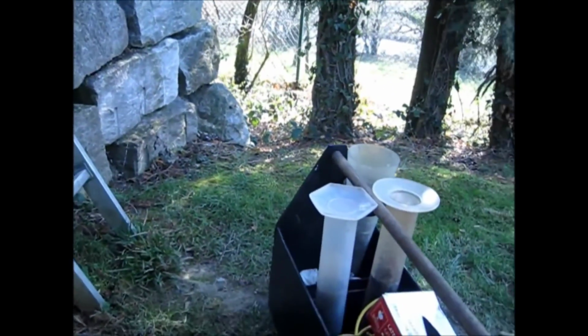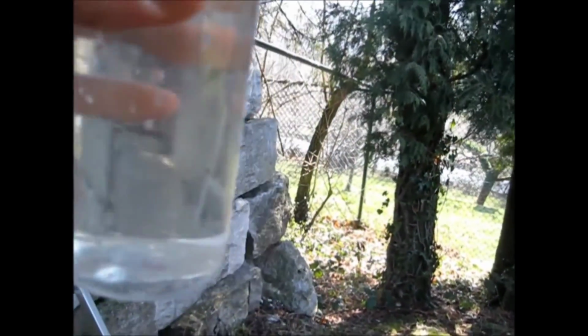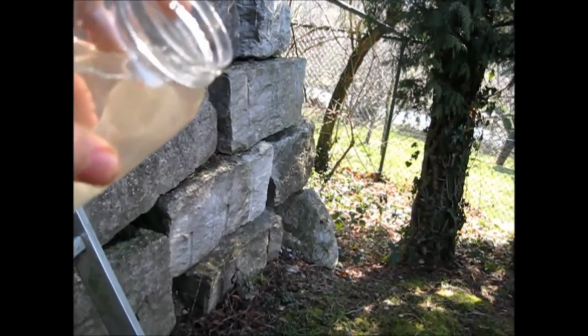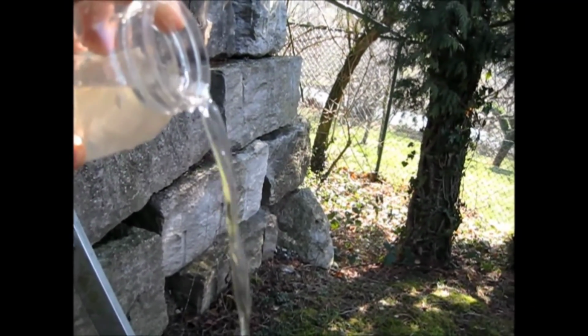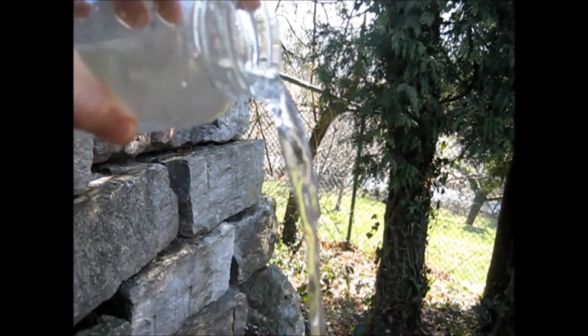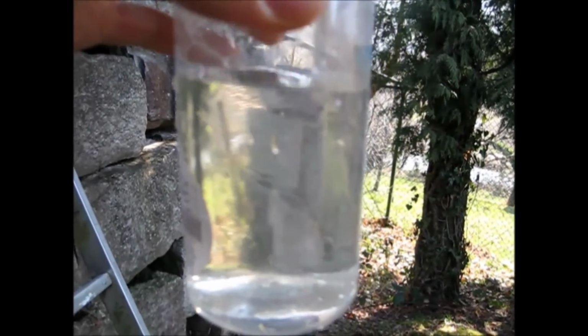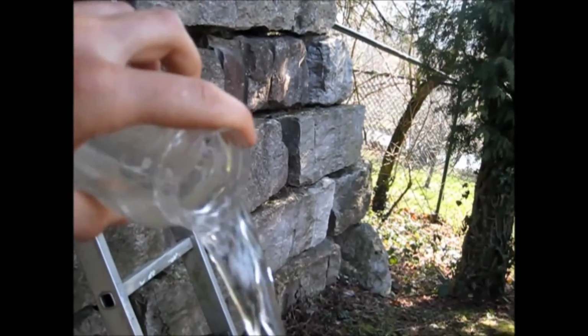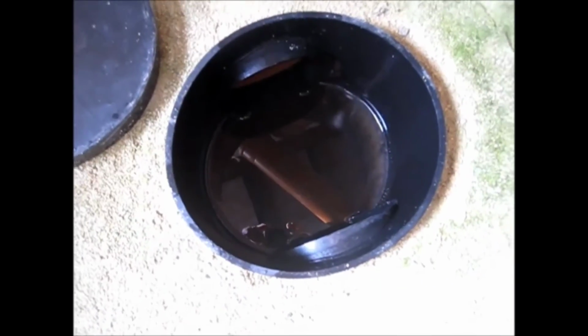Here we take a sample directly out of the discharge, and you can see that the water is very, very pure. COD values below 40 are normal. Ammonium concentration is below the measurable area. Phosphorus is removed biologically and bound to the sludge. There is no disturbance in color in this sample. No odor at all appears.